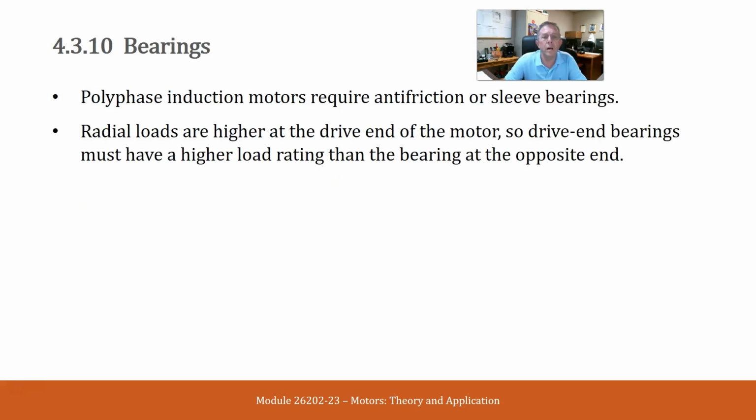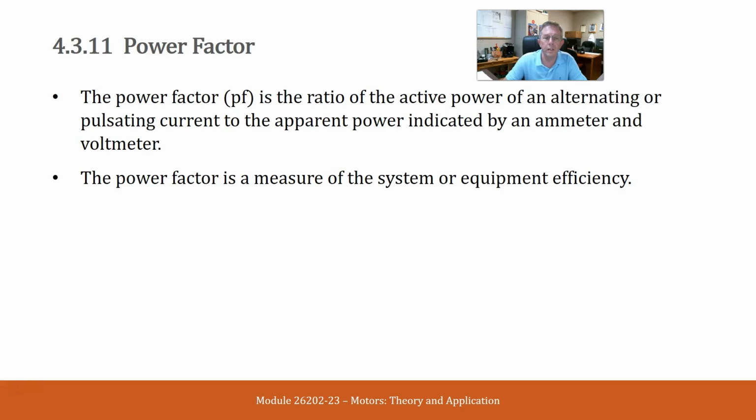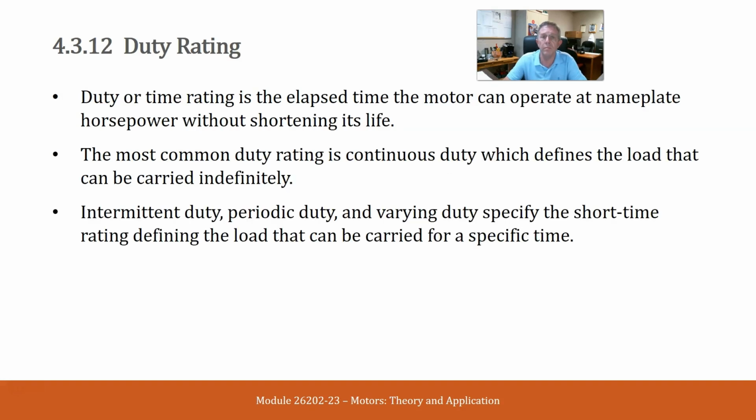Bearings. Polyphase induction motors require anti-friction or sleeve bearings. Rated loads are higher at the drive end of the motor, so drive end bearings must have a higher load rating than the bearing at the opposite end. Power factor. The power factor is the ratio of active power of an alternating or pulsating current to the apparent power indicated by an ammeter and voltmeter. The power factor is a measure of the system or equipment efficiency.